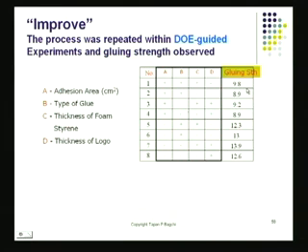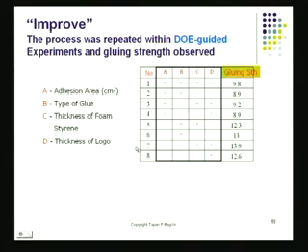When all these experiments are done, remember this side of the matrix is an orthogonal matrix. It's an orthogonal experimental design scheme, which is what I've utilized to show you this matrix on this side. It has 8 trials and 4 factors being varied according to the settings here, and these are the resulting numbers. The first experiment, done at plus, plus, plus, minus, gave us a gluing strength of 9.8 pounds, then 8.9 pounds, then 9.2 pounds, and so on. And this one gave 12.3 pounds, then 13 pounds, 13.9 pounds, and 12.6 pounds.